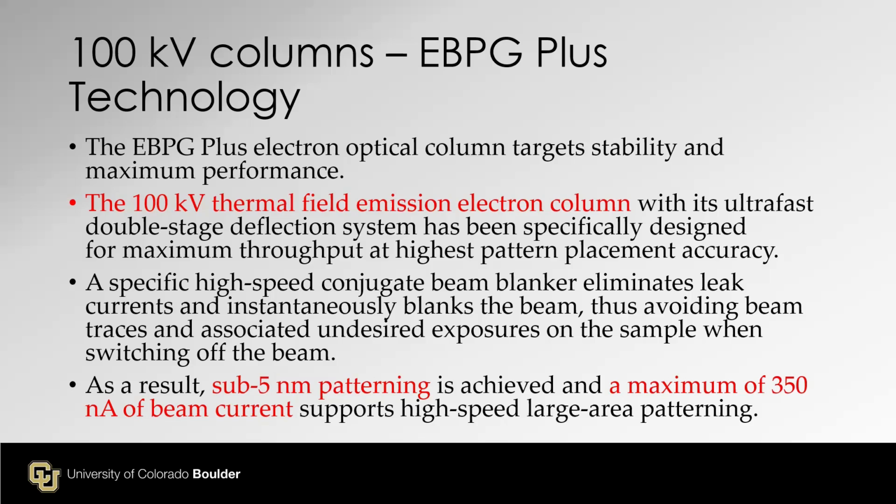But for the E-beam direct writer, we can use much higher beam current when the resolution is not important, and it can change the beam current during the writing. You can specify the beam current. So for high resolution, you can use a different beam size. And when the resolution is not that important, you can increase the beam size. So it's very flexible, automated.